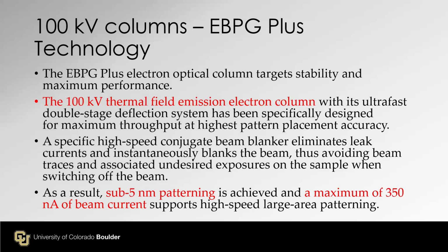So let me talk about SEM. For SEM imaging, to take a nice quality picture, we don't need a very long time, not 1 hour. So column stability is not super important for SEM as a characterization tool, but for the E-beam writer as a fabrication tool, that is super important.